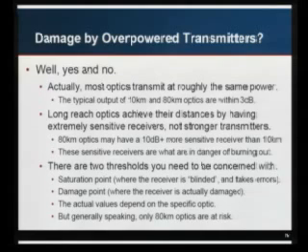So there's basically two threshold points that you actually care about. One is the saturation point. That's where the receiver's blinded. You can actually send a signal that's so strong that it doesn't cause any damage, but it can't be read, and so it just causes bit errors. And then you get to a point that's actually the damage point where you can actually burn out the receiver.